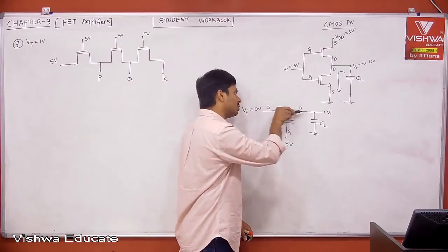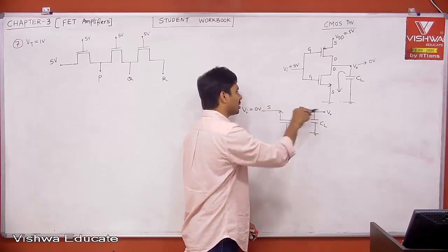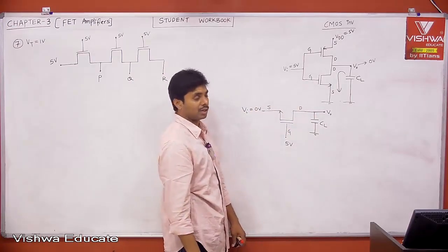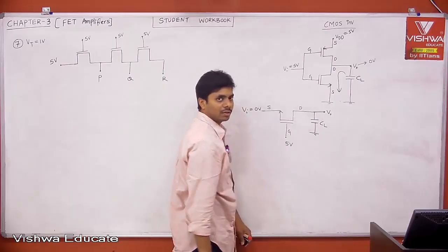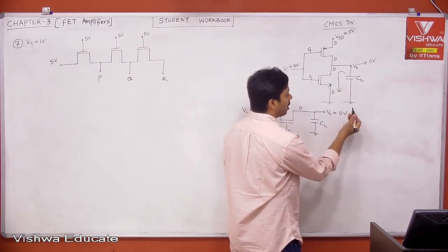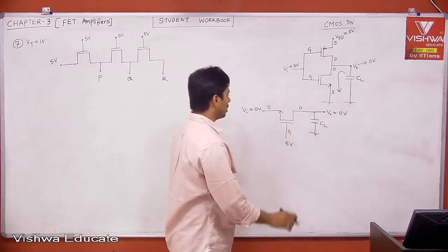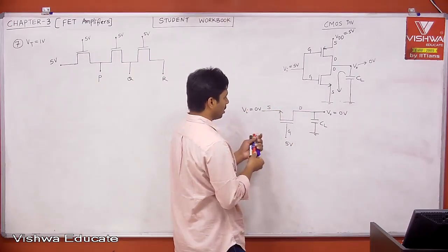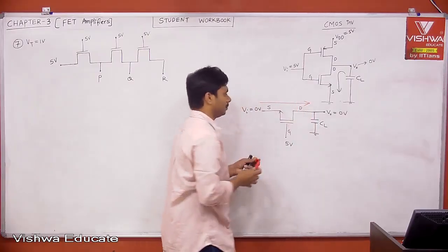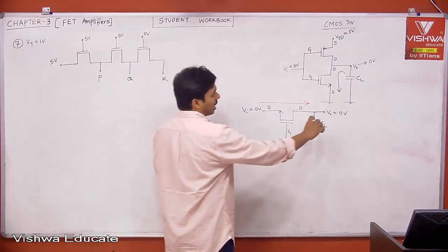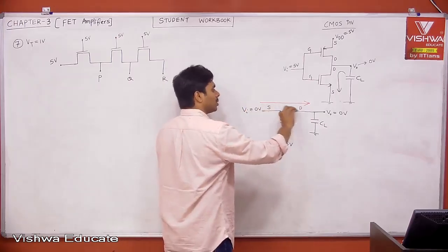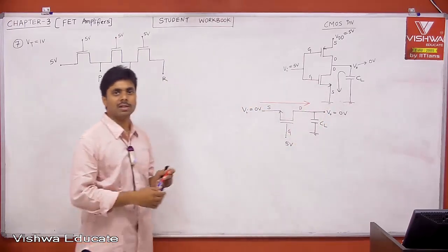Now we are trying to pass this 0 from here to here. That's why this is called a pass transistor. It is passing from here to here. Fine. Therefore, tell me, what is your V0? Ultimately, your V0 is equal to 0 under steady state. You will get 0 volt from here to here. Even if it has some voltage, that will be discharged through the transistor to ground, but whatever may be the case, 0 is coming to the output. That is what your pass transistor does.